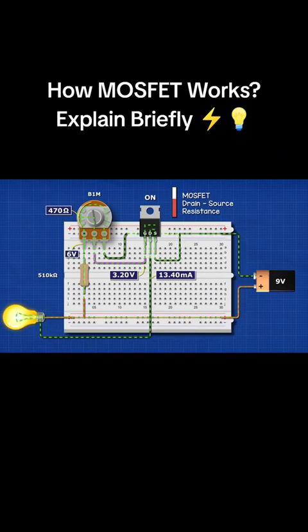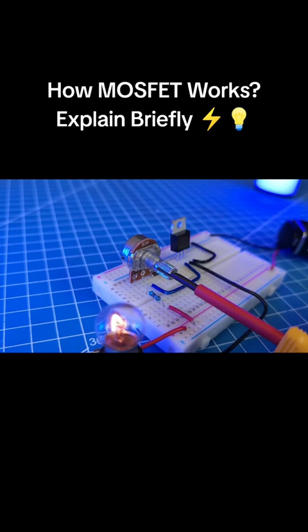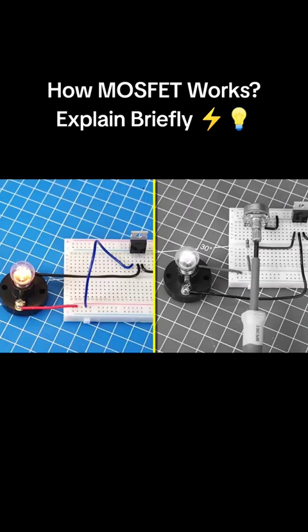As the gate voltage reduces, the MOSFET begins to deactivate, increasing the resistance between the drain and source. And so the lamp becomes dimmer and dimmer until the MOSFET completely deactivates and the current is blocked. So we can turn a circuit on and off, or we can vary the gate voltage to vary the resistance.